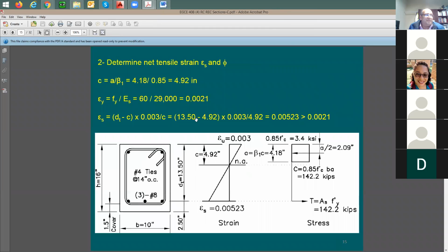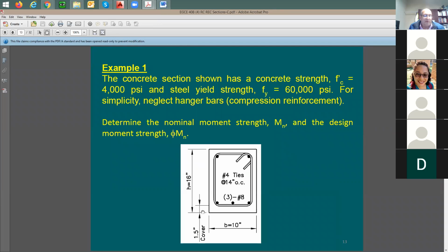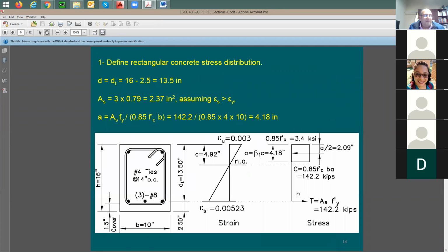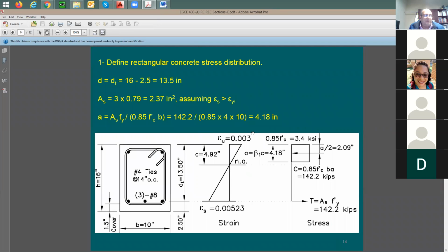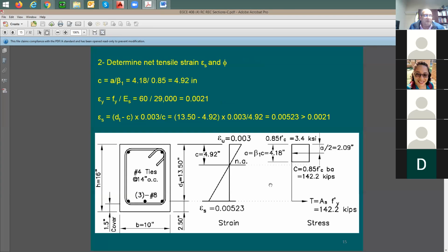In the first example that we have done for the concrete design, the steel with this amount of reinforcing was yielding, and we were able to confirm this. You remember this discussion? We have this assumption that the steel yield strain is going to be exceeded by the actual strain in the steel, which is 0.05, more than 0.002. So we said we're good, and everything was great.